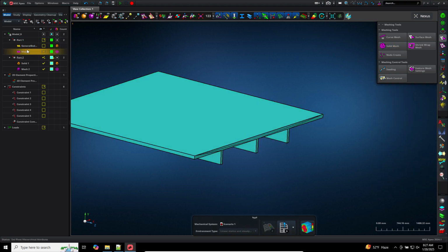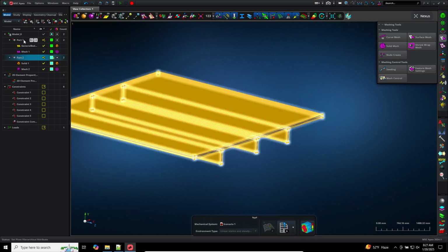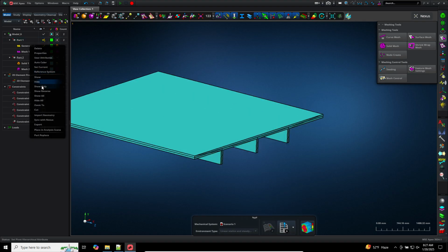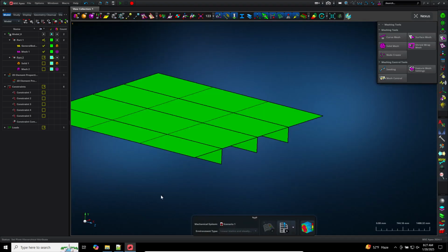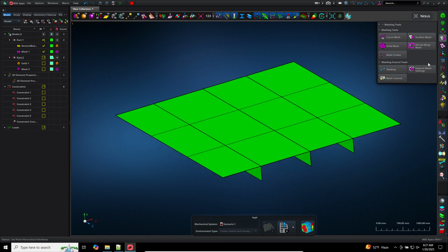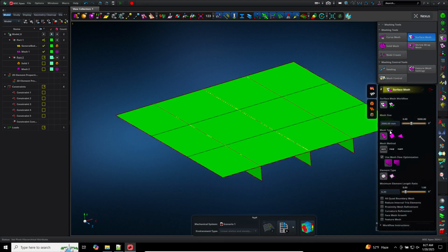One quick comment. Let's go back to part 1, actually. I forgot to mention something. Once you're comfortable with the whole procedure, you can now use a finer mesh. So let's go to the surface mesher rather.